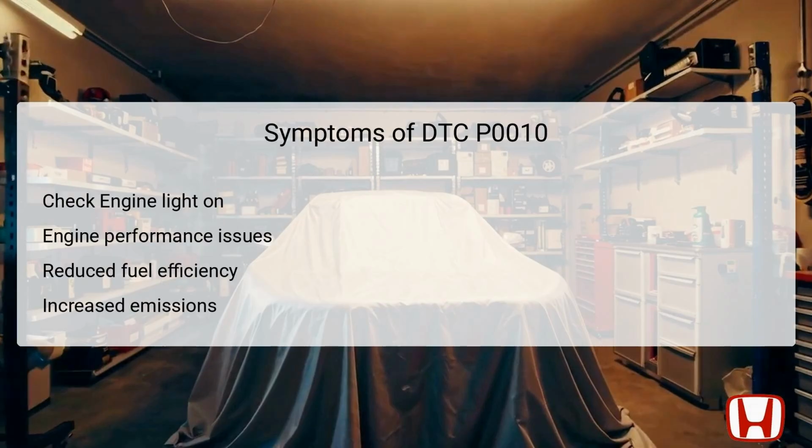Additionally, reduced fuel efficiency may become apparent due to the engine not operating within its optimal parameters, leading to higher fuel consumption. Increased emissions can also be a direct consequence due to improper air-fuel mixture as a result of suboptimal engine timing, contributing to potential failure during emissions testing. By recognizing these symptoms, technicians can pinpoint issues more accurately, guiding them in the troubleshooting process.